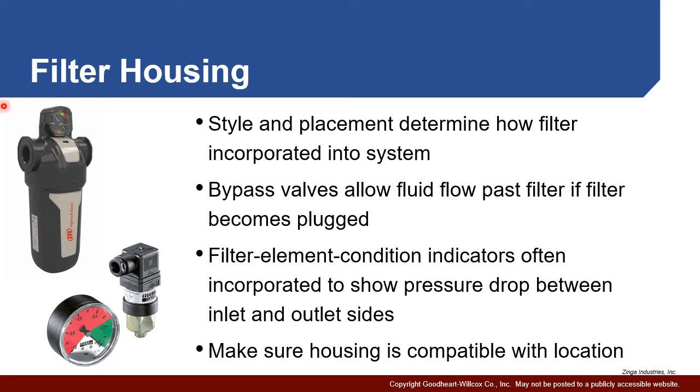And we can see, for example, in here and down below, we can see a pressure indicator. And essentially, it tells us as the pressure goes up, this is it functioning well. It's going to go through this area here, white or yellow, meaning it's getting close to its service life. And once it reaches red, we want to be able to replace that filter or clean that filter.